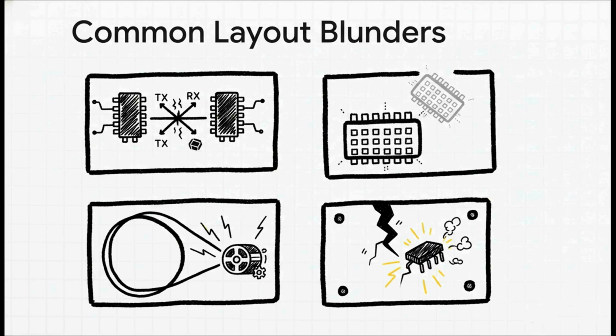Even worse is a mirrored footprint, where the whole chip is laid out backwards. Or how about long SPI traces that act like little antennas, picking up noise from a nearby motor and causing random data corruption that looks exactly like a software driver bug?